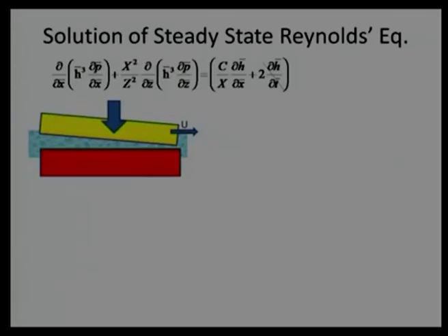We can do some sort of statistical analysis. We can assume the pressure will vary within some band. So, for starting purposes, it is always advisable to start with a steady state analysis, understand the pressure generation, and see what results we are able to get, and what kind of modification in design we should implement, so that we can get much more desirable results.